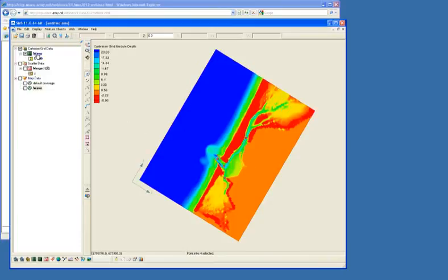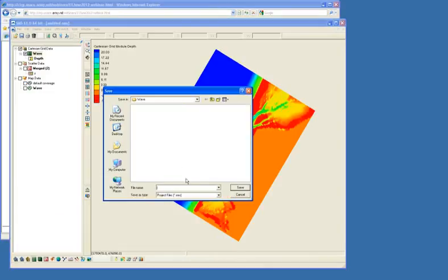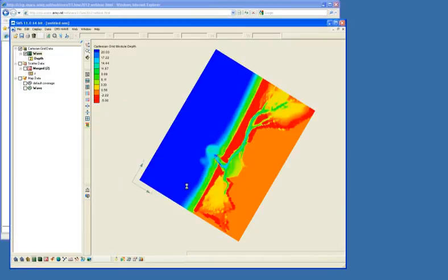At this point, since everything is how I want it, I could go up to the wave model and either file, save, CMS wave, and then I'll be asked for a file name, or we can do like we've previously done and save a new project. And I've just been using a prefix of webinar for these saves, so I just tried that.